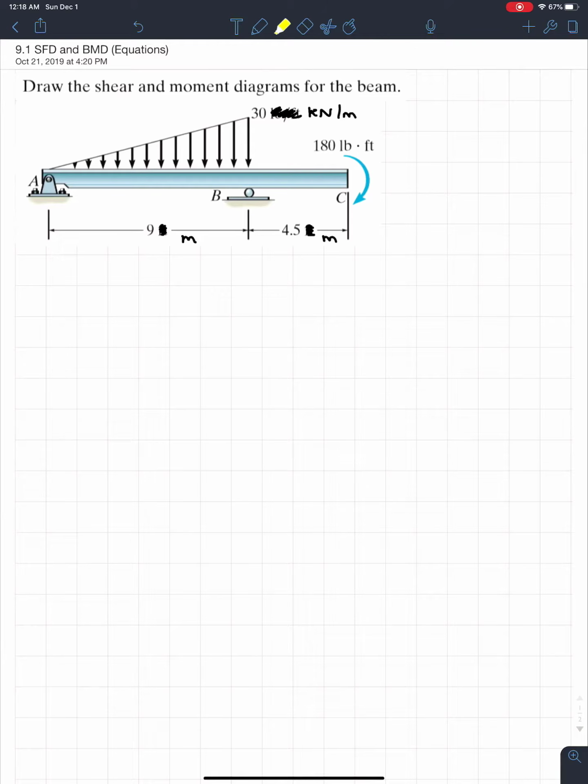As you remember in a truss, we'd cut a bunch of the truss members and replace the members that we cut with a single axial force. Now we do the exact same thing for beams, except, as you know, we have three forces: a shear force, an axial force, and a bending moment. In last week's videos, you learned to solve for those values at single points. But now we're going to learn how to do it for every single point across the segment. So it's a little bit more tricky.